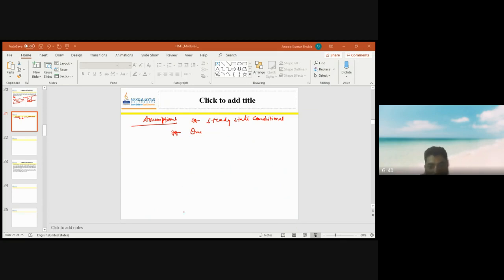All the parameters are given. Q we have already calculated as 1.8, ln of 0.125 upon 0.0025, upon 2 pi into 0.3 into delta T, which is simply 200 minus 150 degrees Celsius.